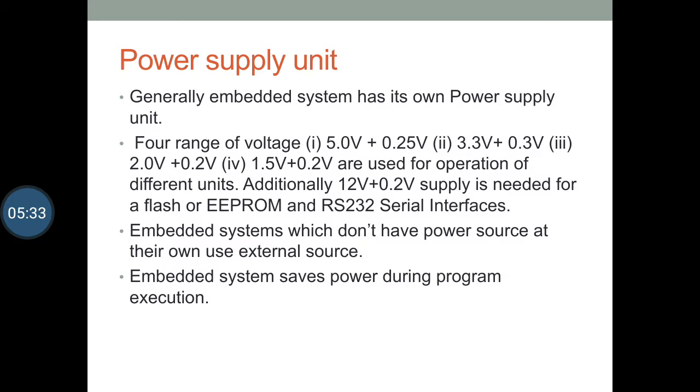Supply of voltage to the chip depends on the number of pins provided in the chip, which is generally in a pair, supply and ground. A processor may have more than 2 pins of VDD and VSS, which are responsible for distribution of power and reduction of interference in all the sections. Supply should separately power the external I/O driving port, timers, clock, and reset circuits.